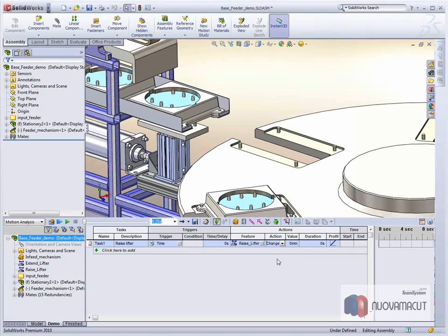And it's a servo motor, which means it's positional based. So we can specify a particular value, say 112.5 millimeters. That's how far it's going to move relative to its current position. We specify a time that it should do that operation over, and then an interpolation method. Cycloidal just means it starts and finishes with 0 acceleration.